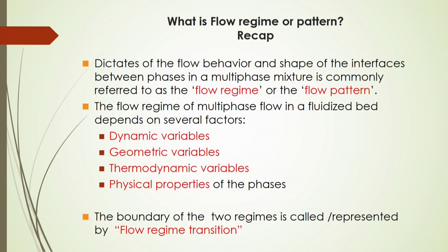The flow regime of multi-phase flow in a fluidized bed depends on several factors like dynamic variables, geometric variables, thermodynamic variables and physical properties of the phases. Dynamic variables are like the flow rate of the gas, liquid, or even if solid is in continuous mode, then the solid velocity.